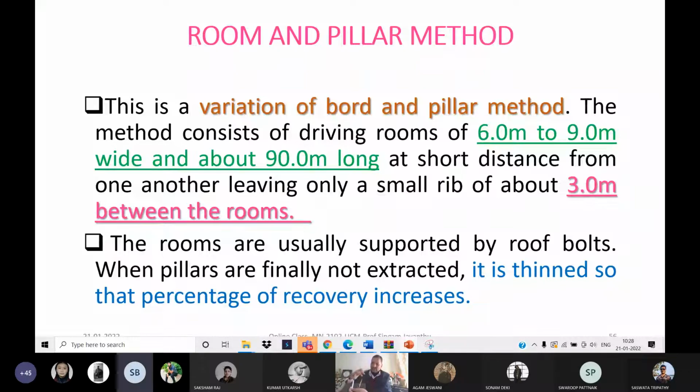You should say, Yes, sir. I can understand, right? Okay. So if you consider this as a pillar, you made these two splits. This is the most conventional, I mean traditional, way of extraction of our pillars, splitting and slicing. These are the splits. This is a split again, 4 meter width or 4.2, whatever. Then we are slicing it. And when you are slicing, this is a slice. This left out portion is a rib. So this rib we are robbing, or excavating, or thinning down.